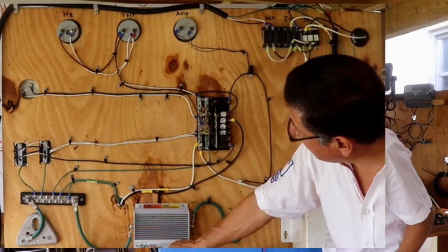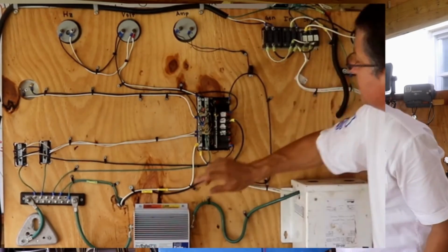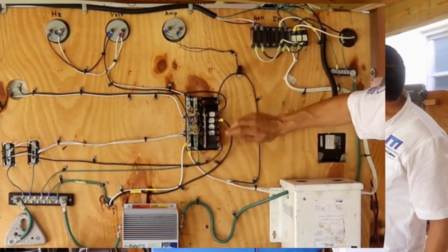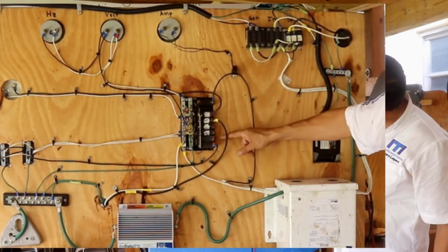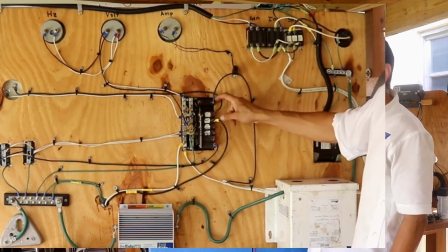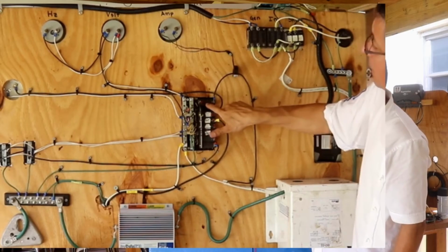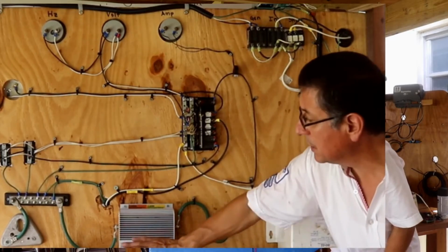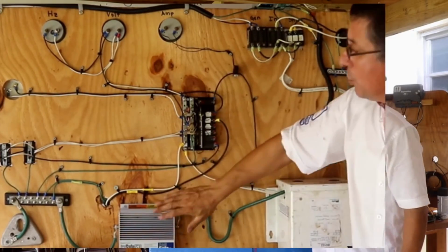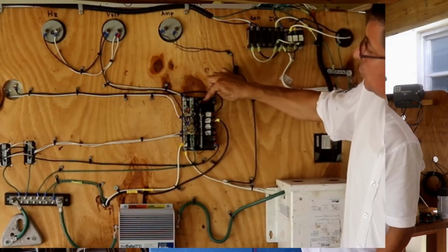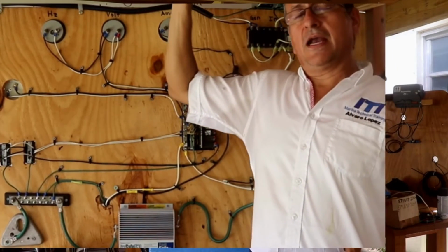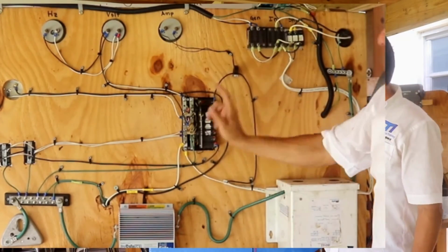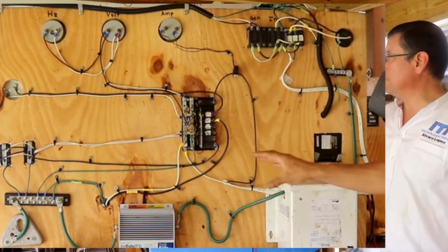The capacity of the galvanic isolator in amps should be exactly the same as the capacity of the main breaker on the AC panel. This is the main breaker, this is the AC panel, and those are the individual breakers. The capacity of this main breaker, in this particular case, is 30 amps, and the capacity of the galvanic isolator is 30 amps. This one should be equal to this, and also the capacity of this and this should be equal to the capacity of the output breaker of the generator. 30 amps, 30 amps, 30 amps. It's exactly the same for all of them.